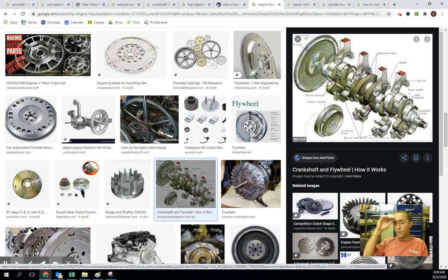Also, when you think about it, your engine is doing a lot of work, right? You have forces everywhere throughout the engine. Those pistons are constantly going up and down. But when those pistons are going up and down, only one of the four strokes actually creates power. We have our intake, we have our compression, then we have our power stroke, then we finish off with our exhaust stroke. The power stroke's the one that's doing all the work.